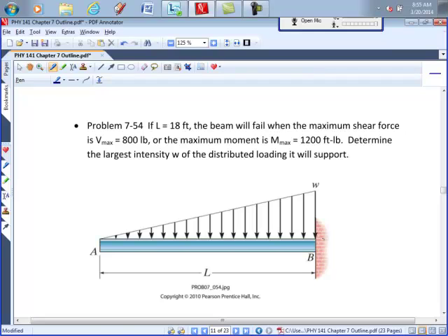And in fact, if I find the reactions at B, I'm not going to use them to find those shear and bending moments on the left section anyway, because they're not acting on the left section. So I'm not going to do that this time. And in general, on a cantilevered beam, you don't have to find them. By the time you do the shear and moment diagrams, the values we have at the end are going to be the reaction forces at that support end. So our first step this time is actually just to take the section, an arbitrary distance x from A.